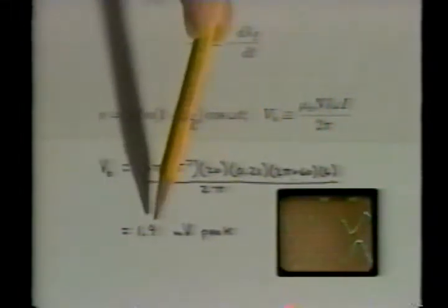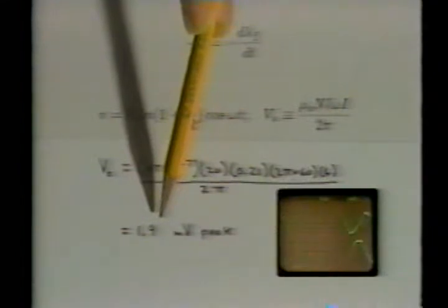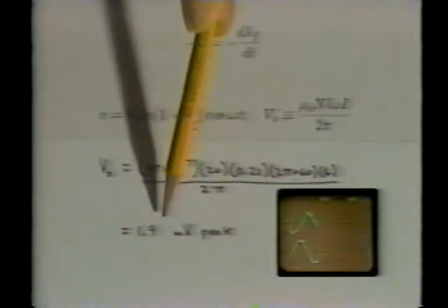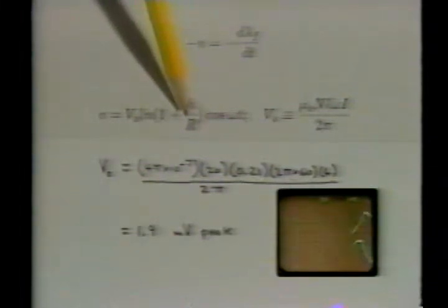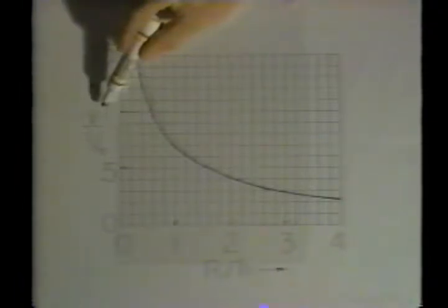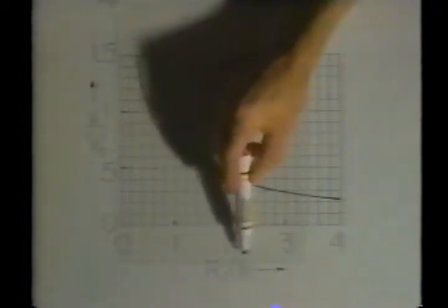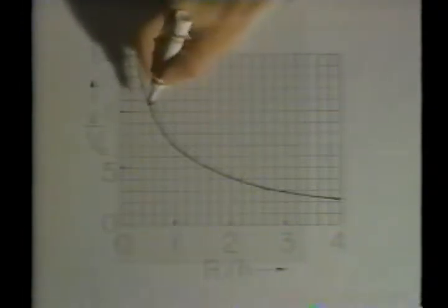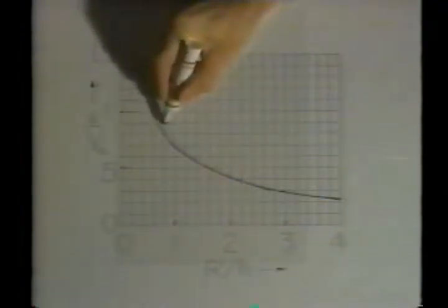Here is the normalized voltage predicted by Faraday's integral law as a function of normalized spacing. Our data point goes here. These are normalized voltages measured at other spacings. The discrepancy is due to the large sensing coil size as compared to the length of the current carrying wire and the proximity of the nearby return current wire. Faraday's integral law predicts the voltage induced at the terminals of a coil that links a time-varying magnetic flux.